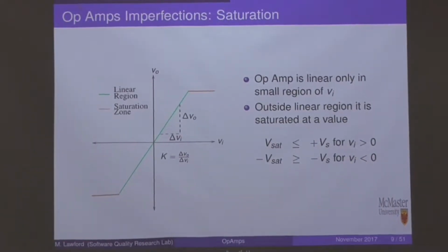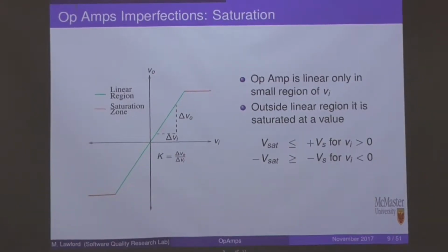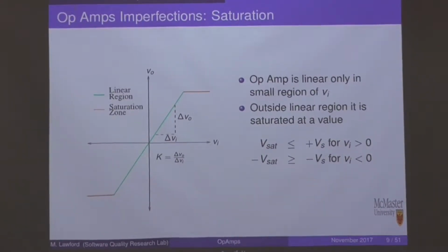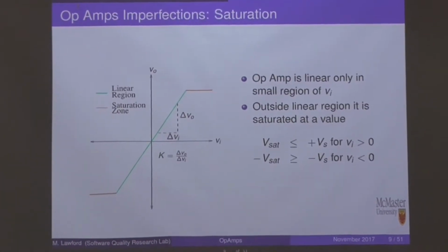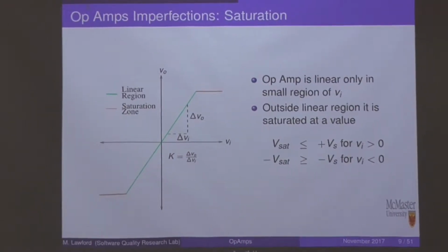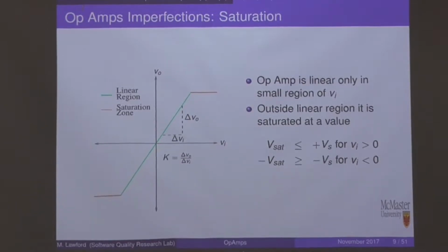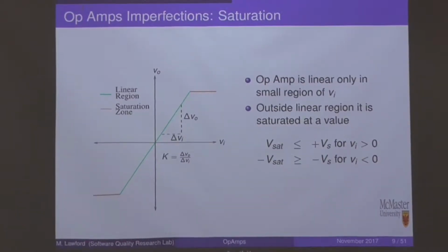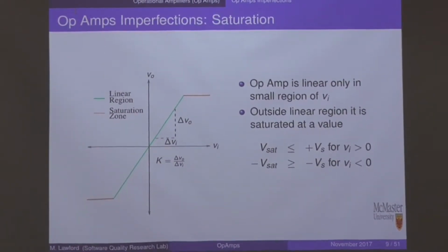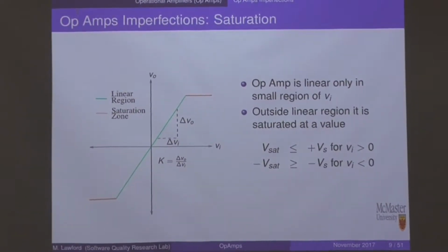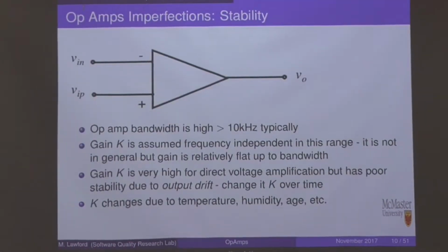In the case of 10 to the 6, a microvolt turns into a volt through an operational amplifier without any feedback. So this is why we typically do feedback, because factors of 1,000,000 or 1,000,000,000, while cool on paper, are far less practical than scaling factors of 3 or 4 or 10, or even 1,000 is a lot more practical. Good.